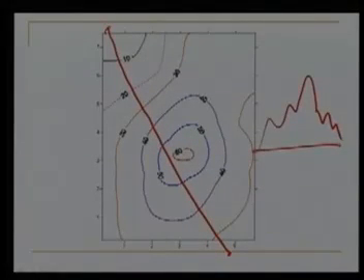The next application is about drawing the profiles from the contour map. Why do we need the profiles? We have already discussed. Let us say, starting from this point here, we want to go here, and we want to see how the elevation of the ground is changing between these 2 points. We have seen some examples of use of this in road construction and in many other places. So many times we desire to draw the profile along a particular line. The procedure is very simple.